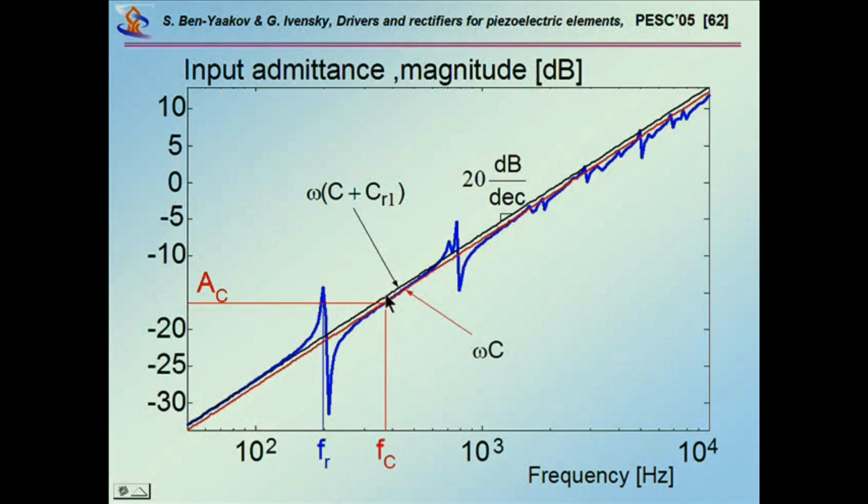This capacitance is going down by a bit because at this point we are losing the capacitance of this resonance, because we are now at a frequency above the resonance, and therefore the impedance here is already high, because the impedance of the inductor is large, so we don't see this extra capacitance.